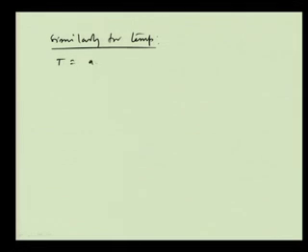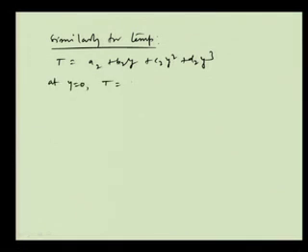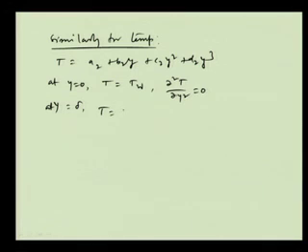Similarly, for temperature, exactly the similar thing you can do. So, we will assume that T is equal to a 2 plus b 2 y plus c 2 y square plus d 2 y cube. And then what will be the conditions? At y is equal to 0, we have T is equal to T wall, and also we have del 2 T by del y square equal to 0. That is what we have seen, and at y is equal to delta, we have T is equal to T infinity, and we have del T by del y is equal to 0.